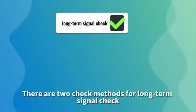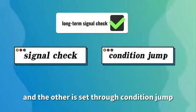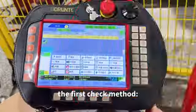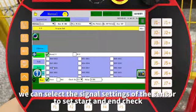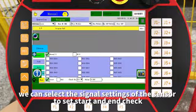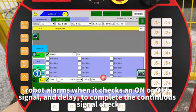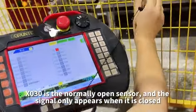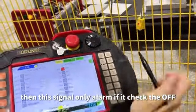There are two check methods for long-term signal check. One is set through signal check, and the other is set through condition jump. We can achieve continuous check of signals through these two methods. The first method: click Program, Editor, there is a check here. We can select the signal settings of the sensor to set start, and then check whether the robot alarms when it checks an ON or OFF signal, and set the delay to complete the continuous signal check. For example, X030 is a normally open sensor, and the signal only appears when it is closed. Then this signal only alarms if it checks OFF.